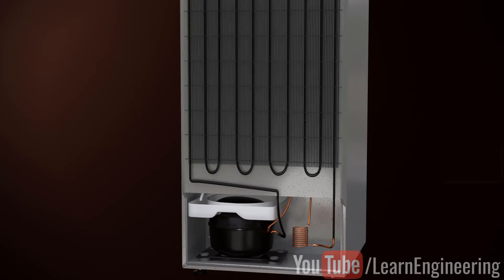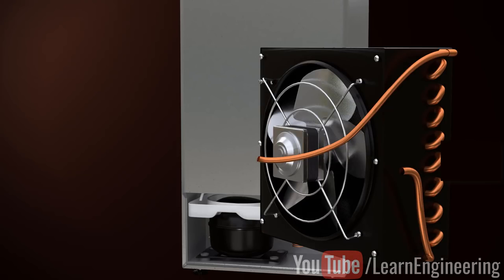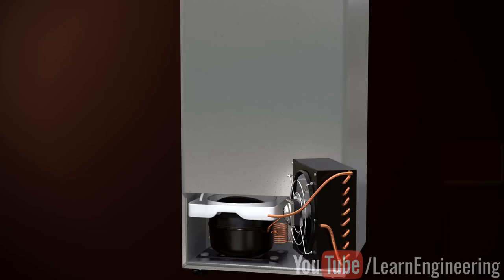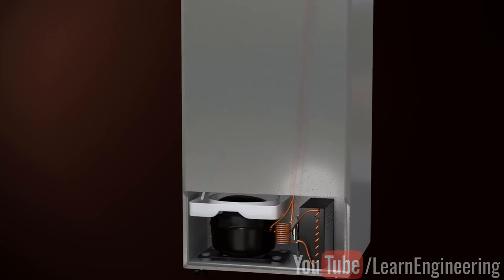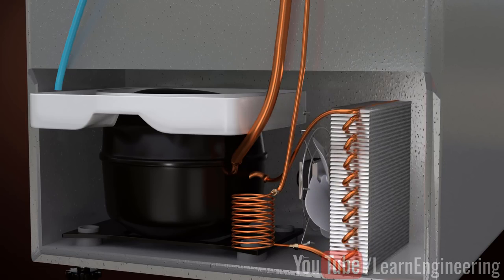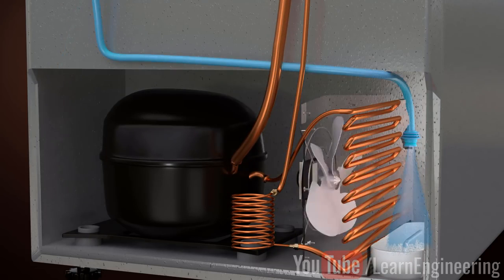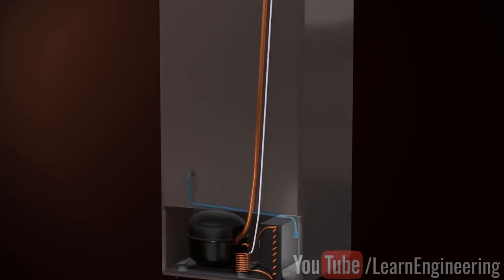Moreover, in modern refrigerators, you won't be able to see the condenser fins at the back of the refrigerator. Instead, they use a compact condenser arrangement. This compact arrangement is assisted by a cooling fan, and the same heat rejection purpose is achieved here. The hot air expelled by the fan can be used to effectively evaporate the water condensate formed during defrosting. The improved refrigerator looks like this.